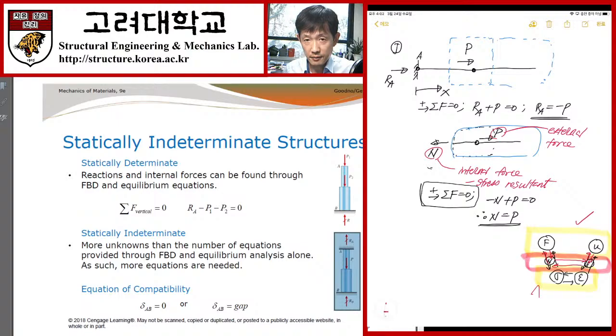But if you have a shortcut formula, like the elongation delta is equal to the length times the internal force divided by the elastic modulus and the cross-section area, then in that case, yes, we don't have to consider stress and strain. Okay. We can accelerate our calculation. So now I have the information of this internal force here. Okay, so I want to consider the elongation directly.